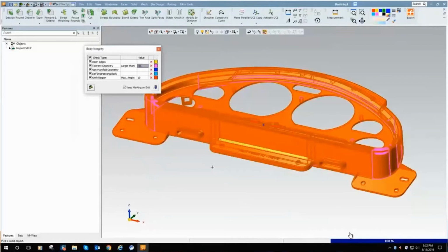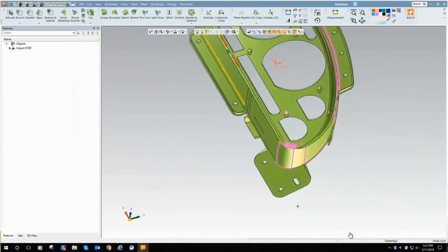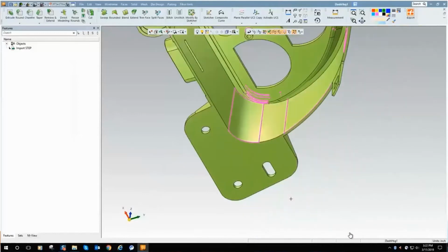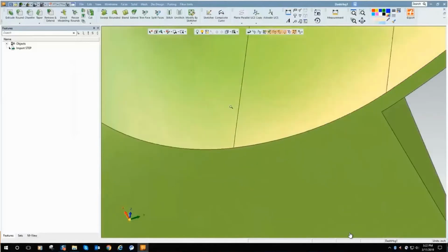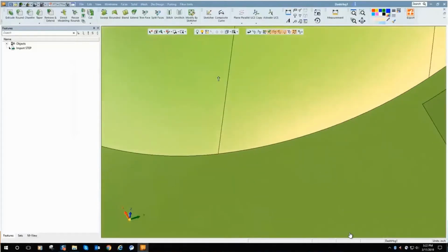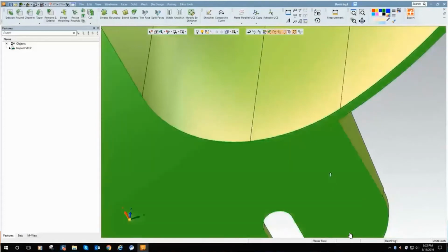It's expected because no geometry is absolutely perfect everywhere. So if tolerant edges are a normal condition in any data, why are they worth checking for? And the answer is related to what the shaded display cannot show. The system has to display the solid part as it was defined to you. So we only see one edge where the faces meet. The real surface math lies hidden underneath.